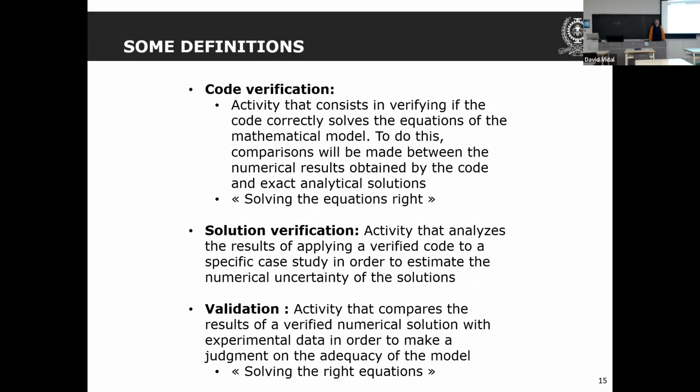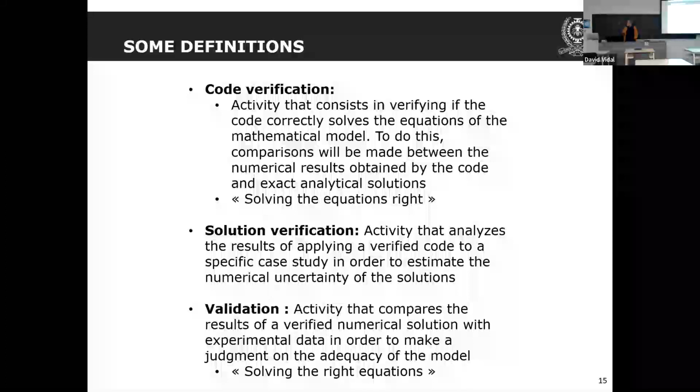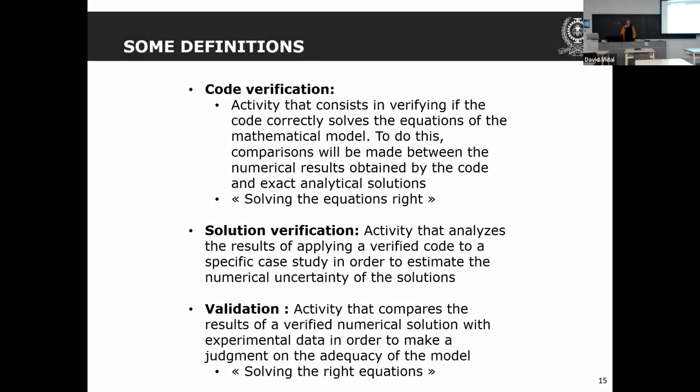A step that is often overlooked or not well appreciated is the solution verification. This verification is not aiming at checking if the code is correct, it is aiming at determining the uncertainty of the simulation that you have done. Can you put a number? I'm getting a given permeability. At which level is this permeability correct? Is it at plus or minus 2%, plus or minus 20%, or plus or minus 100%? So solution verification is aiming at determining the numerical uncertainty of the solution.